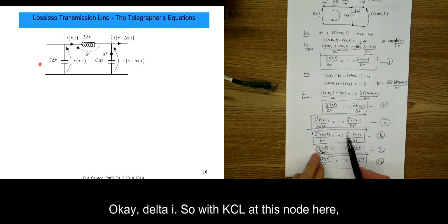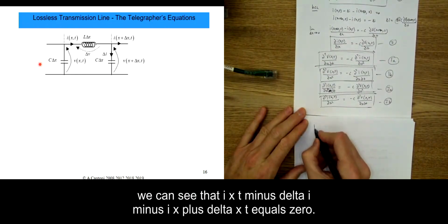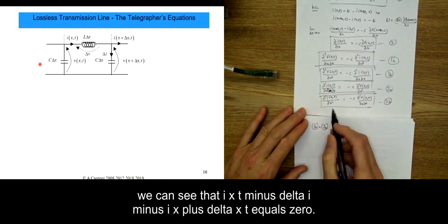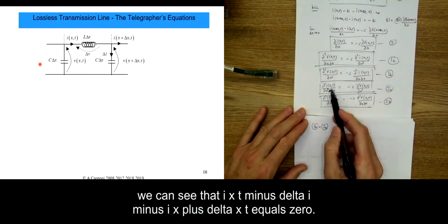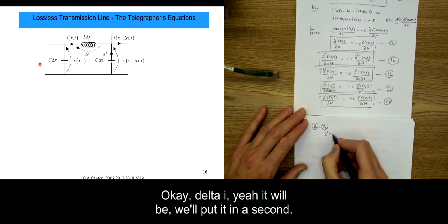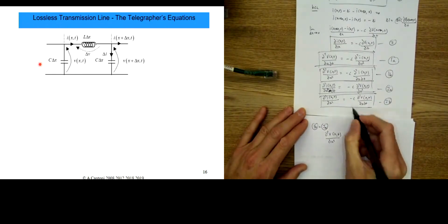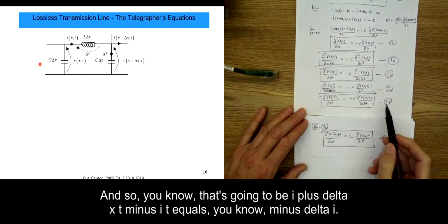So with KCL at this node here, we can see that I(x,t) minus delta I minus I(x+delta x,t) equals 0. Because of delta I, we'll put it in a second. And so that's going to be I(x+delta x,t) minus I(x,t) equals minus delta I.